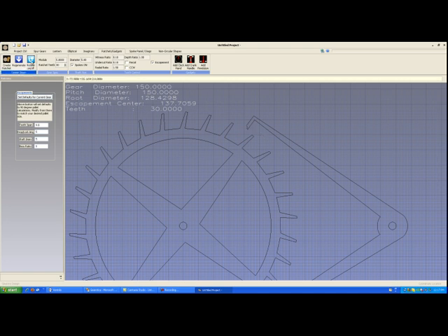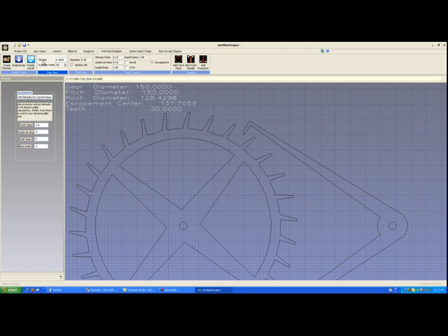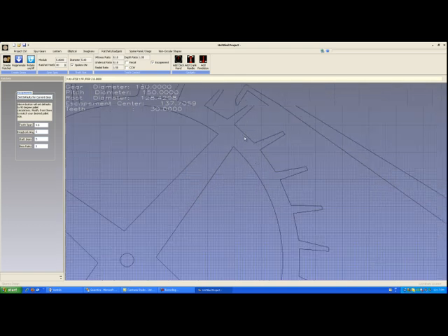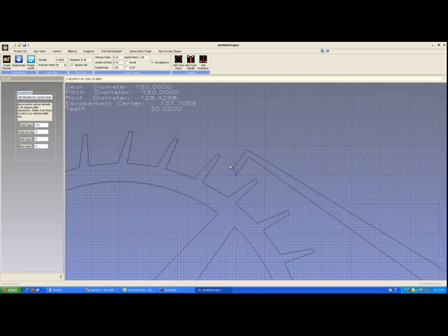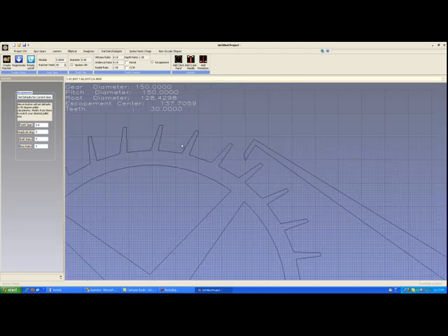The upside of it is that we easily miss every other tooth in the system as we swing in. Watch this tooth as it swings in. You can see it's swinging in about 1/4 of the way through this area. So we're wasting quite a bit because we really want the bottom of this pallet's tooth to just miss the tooth underneath. This will maximize the amount of energy transfer.